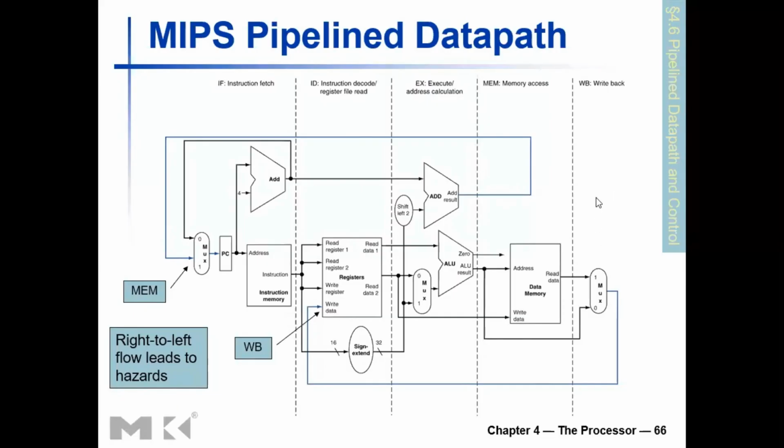So as I was telling, in the memory access stage, you access the memory, and also for branch type instructions, your branch condition calculation result is ready, and the branch address calculated result is also ready. So those things can be used to update the program counter value.